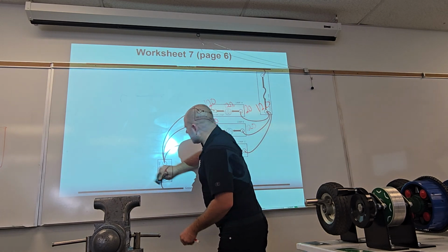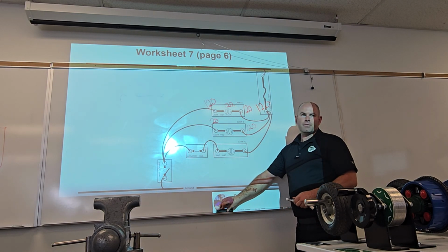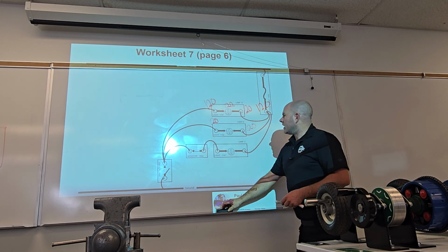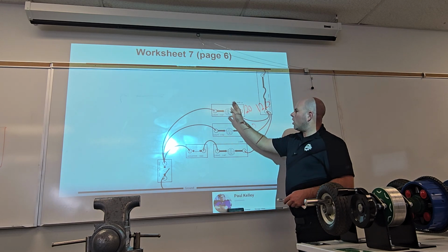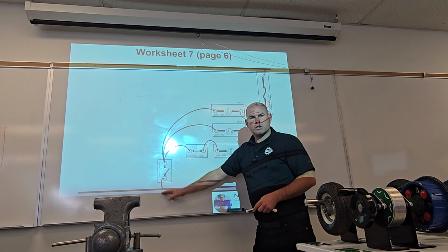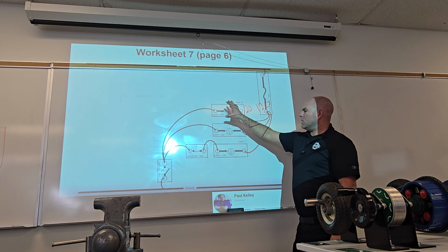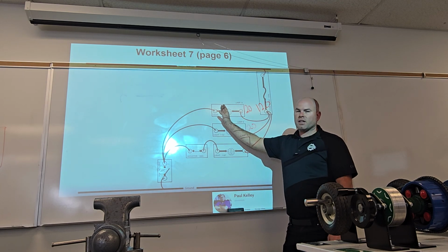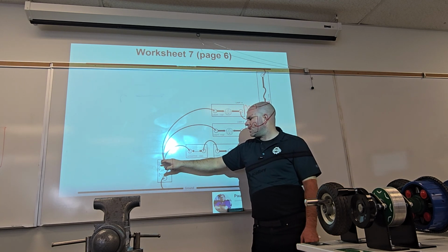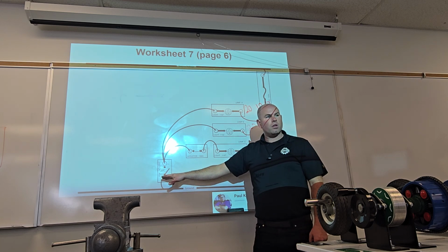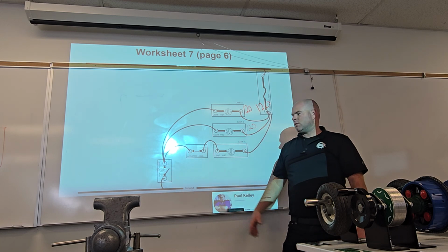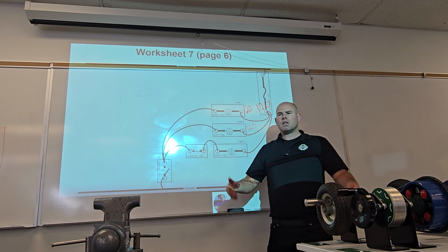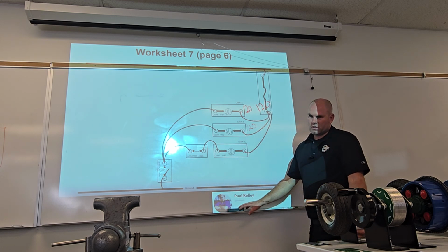So if you were to see this on your midterm, like in a couple hours, you'd be like, oh, I start with 12, I should have 12. Right here, I should drop all 12, and this should be 0. Now, if the switch was messed up, let's say the switch was a full open, this would drop nothing and leave 12 to here. If you had 12 here available and 0 here available, that would mean the switch was open, which in this case, the switch is drawn open. But if you were to close it, it were to still have 12 going in and 0 coming out, that would tell you, hey, this switch is no good. Make sense? That's how we diagnose the car.